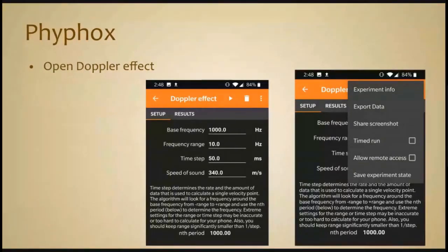And the method is called quadrature. This is the reason that we have two parameters here. One is the base frequency. This is the sinusoid which gets multiplied. And this frequency range is basically the low pass filter which stops the high frequency, and we get to see all frequencies lower than 10 hertz. Typically, that is how it works.